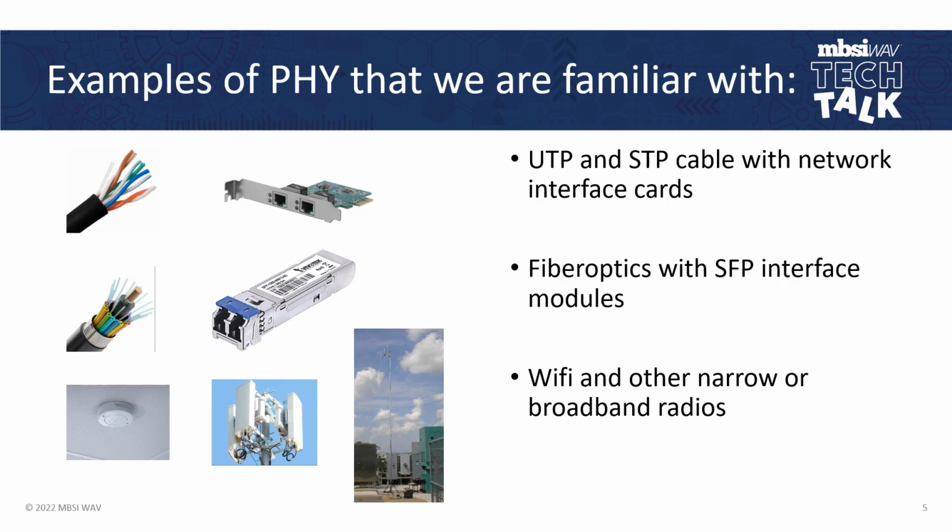The data is sent across the radio link, starting with the data link layer that we're going to talk about later, and received at the other end, decoded and handed back to that OSI stack that exists in the receiver on the other end. Then the receiver on the other end might have to say, okay, I got it. And so exactly the same process occurs going back the other way. So radio is just simply another physical layer network. One device connected to another device.